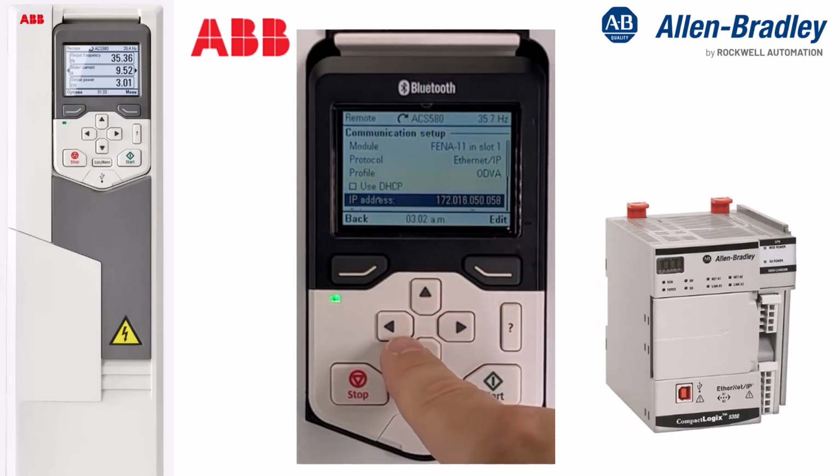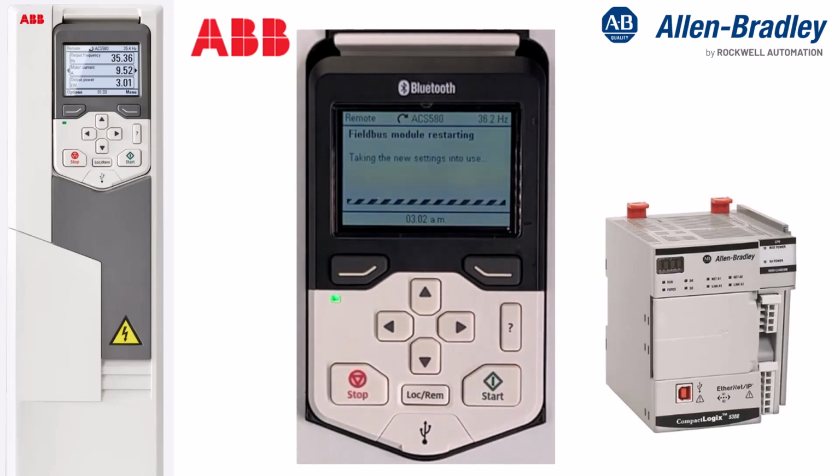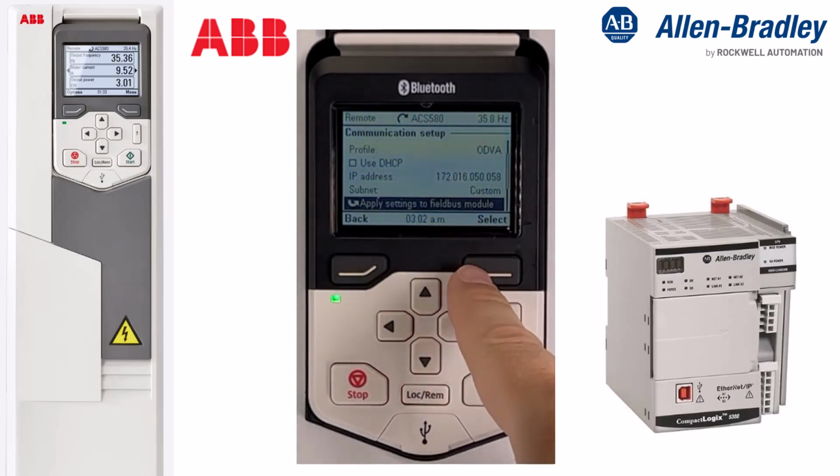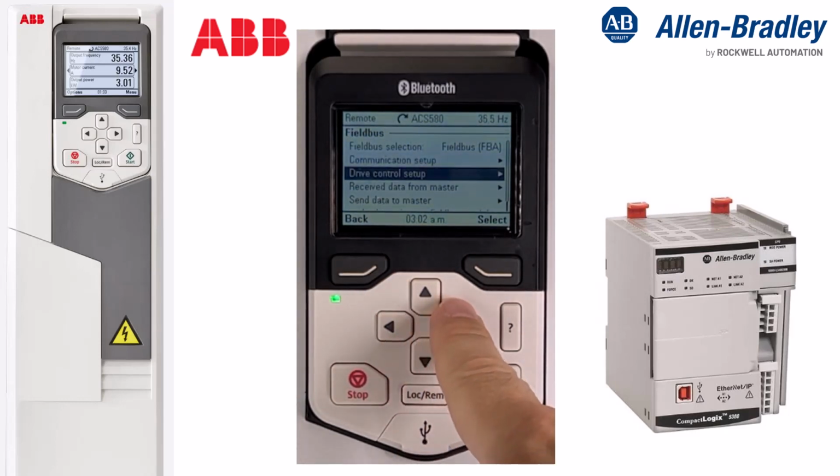After we enter the IP address, we'll click Save and then scroll down to Apply Settings to Field Bus Module. We'll do this several times throughout the process to update all the settings we're changing. We'll then click back and down to Drive Control Setup.